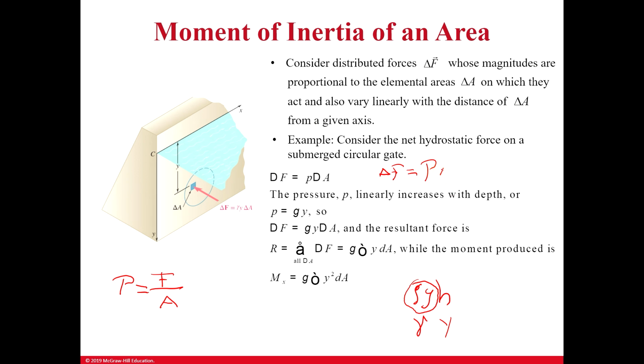And this is going to be proportional for this example to the delta area. Meaning that if you get a larger area to study, the force on that larger area is going to be larger because it's just scaled by a pressure P. We know by now that that pressure P is linear. If you do a side view of this, you remember that wherever the line of the liquid begins, the pressure builds linearly. So that's the distributed force.